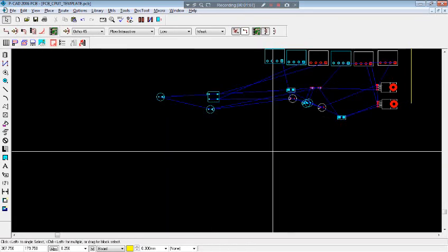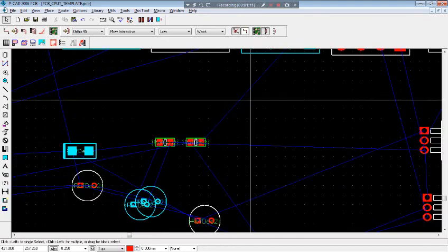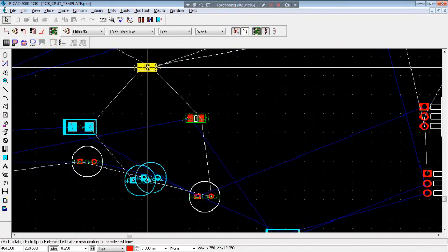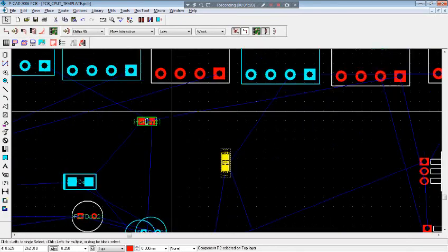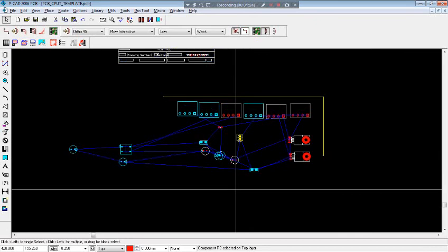As I said in the previous video, if you hold down Control 1, you go back to the first layer, which shows a lot of information. See, there's our ref desk and all these things. If you're busy placing a resistor or capacitor like that, it's annoying. You don't want to see that. You just want to see a component. Okay, so zoom out. I'm going to press 5 again, which is the shortcut for the top layer.